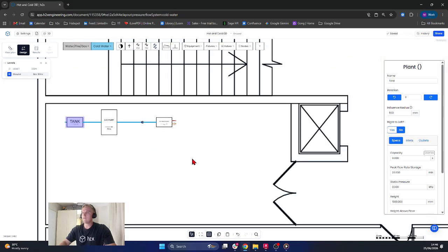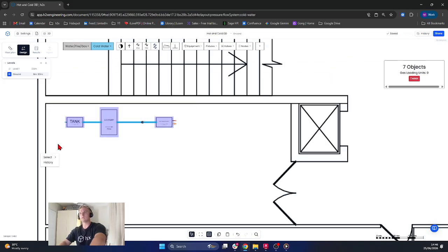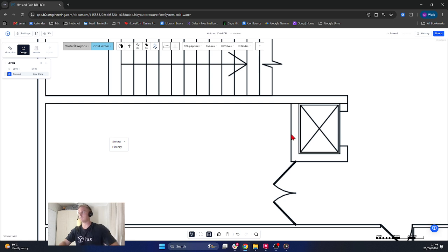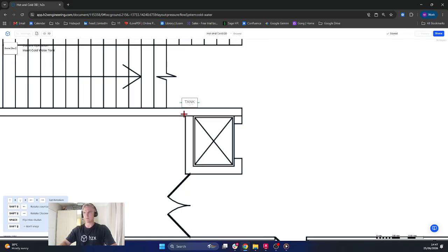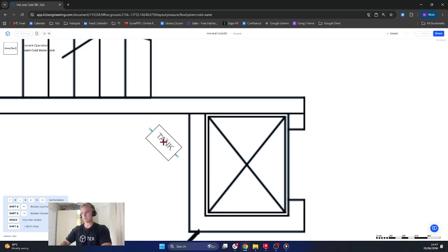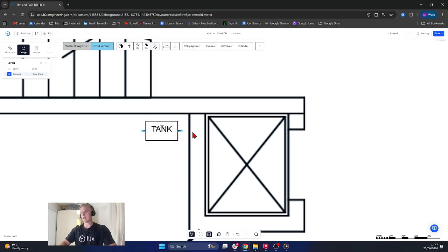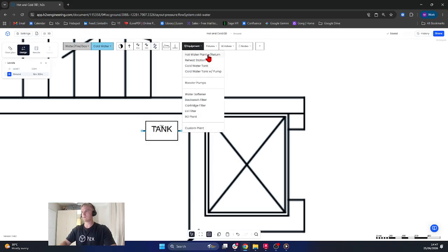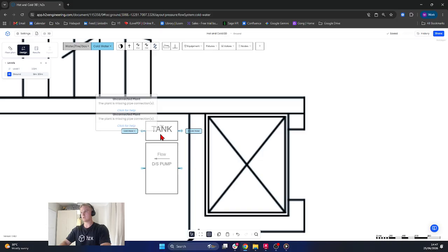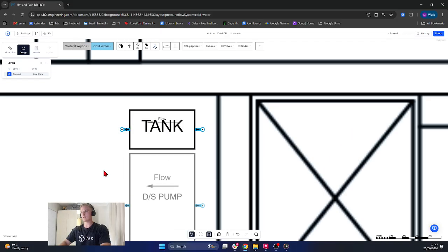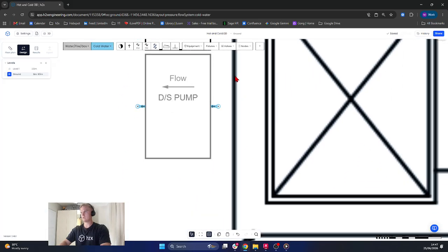Now, if you had to squish these up together, let's say we only had a small corner in here, like a little pen, there is a different approach I would take to connect them up, only because if you're trying to connect in close quarters, it can make it difficult to connect these together. So let's say that needs to wrap around and connect on the other side of this. We need to match the flow directions on here. So you can see that it's got a flow arrow on there. Water needs to come out that way and connect in this way.